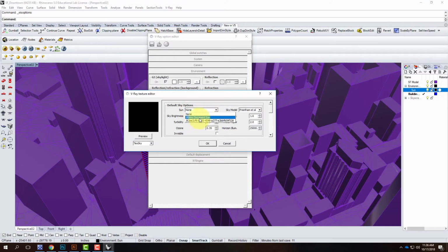And I have two options to pick. One is called the Rhino document sun, and the other is a really long string of numbers. You're going to pick the one that's the really long string of numbers because that's the sun we just inserted into the scene. Question? You must have two suns in your scene, or two lights in your scene. So I'll go ahead and pick it. And there it is. I'll help you find the other light a little bit later on.